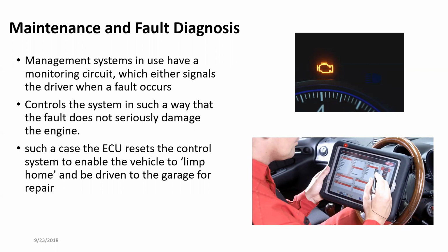From that onward, you have to find out what the proper problem is. To do that, you have to use proper fault diagnostic mechanisms. There are a few steps you can use, like we use a 6-step approach. There are some approaches like that, which we'll be discussing later on. But this particular unit or diagnostic reader cannot directly give you the reason at all times. Sometimes it's right, but not all the time. So it has to be checked very well around it as well.